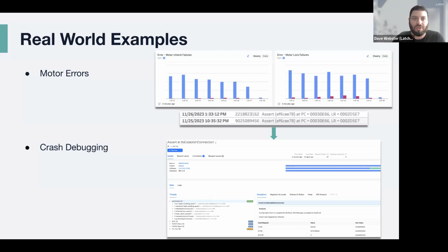If we transition and look over to the core dumps that we get in Memfault, hopefully you can see, if it's a little too small, I apologize. But the issue stuck out like a sore thumb here in that we had unintentionally started multiple IP stack threads, right? That was causing the issue. This is something that would not have been apparent given the previous observability. And so you can imagine, this took us about 15 minutes to figure out the issue, instead of having to go through and reproduce the issue and try and catch the issue and take days or longer to resolve that issue.